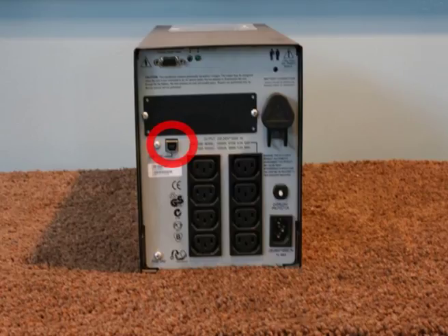These days, a modern UPS also comes with a USB connection to the main desktop. Using the USB interconnection, the desktop can know how much battery power is remaining and for how much time the desktop can sustain on this battery. The moment the UPS is unable to supply the power, the desktop recognizes that and automatically starts the shutdown process. So, using the software which is available on the desktop, it detects that the UPS cannot supply the power anymore to the computer and automatically starts the shutdown process.